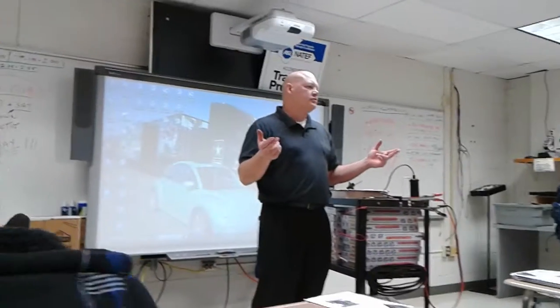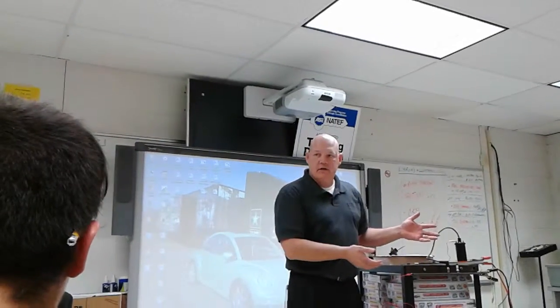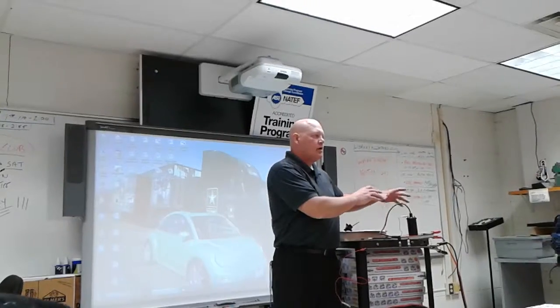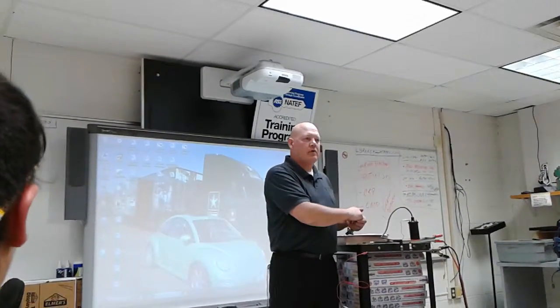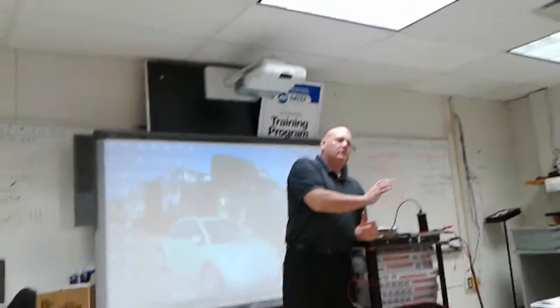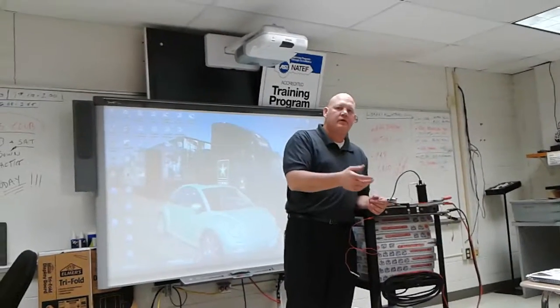what you guys should know, there's two parts to this ignition system. One side called the primary side, one side called the secondary side. The primary side is the low voltage that's creating the magnetic field to begin with. The secondary side is the high voltage, which is the big spark. Now, looking at what I have here, the secondary is the side that contains the high voltage spark, the 30,000 volts.